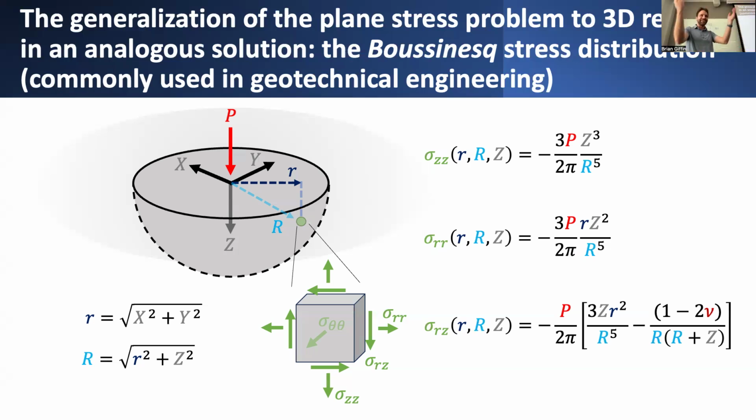That's probably something that if you've taken a class in geomechanics or geotechnical engineering, you're well aware of things like the Mohr-Coulomb failure criterion, which is basically a combined statement that the amount of shear load that a chunk of material, especially like a soil or some other kind of granular media, can sustain is dependent on how much pressure you're putting on it.